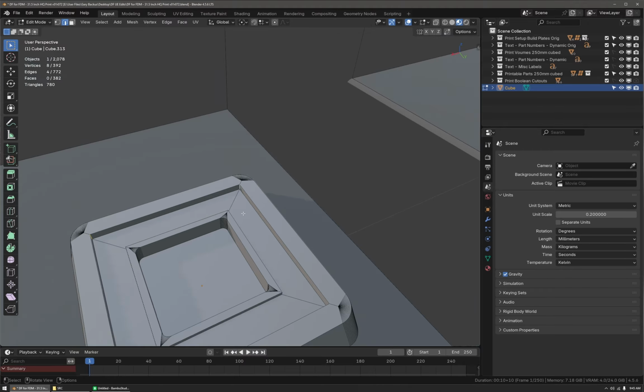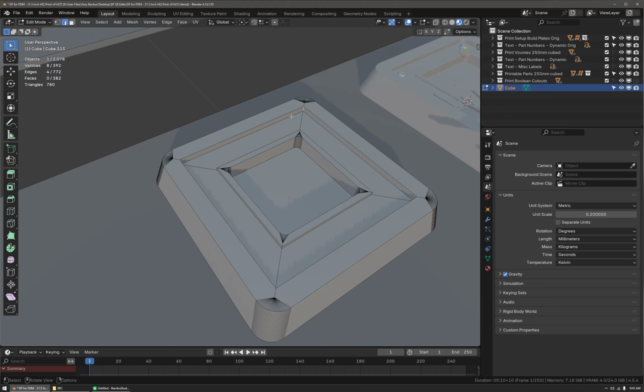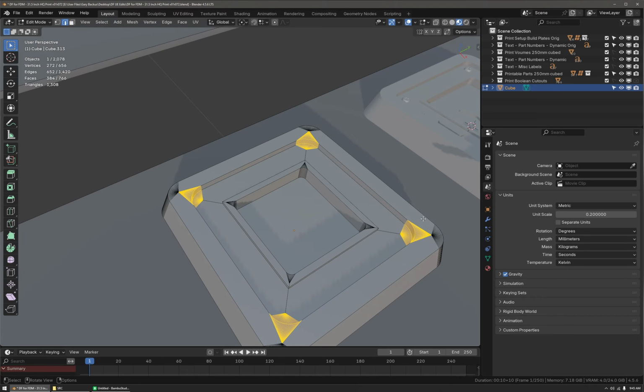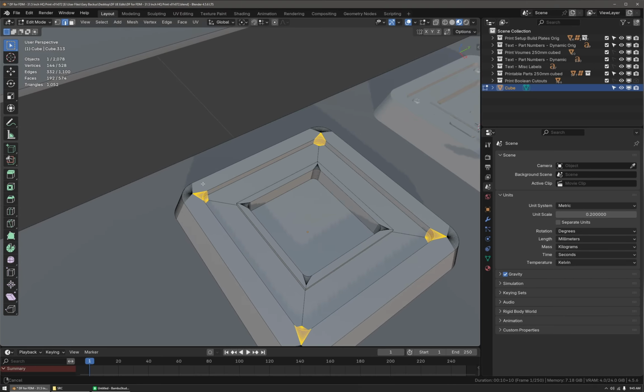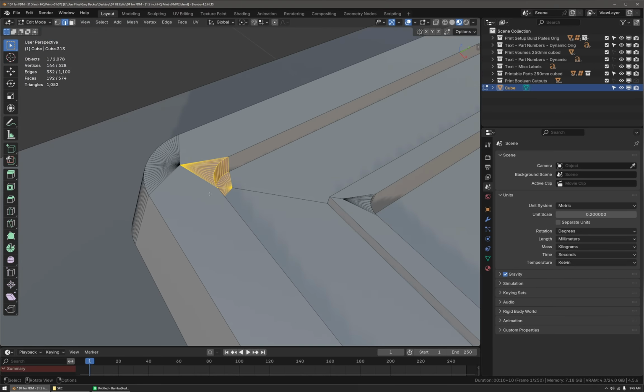So now I'm going to select this as well. And I'm going to press Shift R to repeat that operation, F9 to bring up the command panel or the operator panel. I'm going to choose half the amount of geometric detail so that now the overall density of polygons here is roughly the same. All right, so we've created the general idea of that surface.